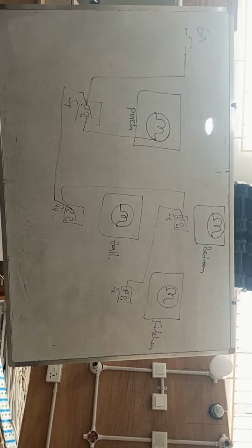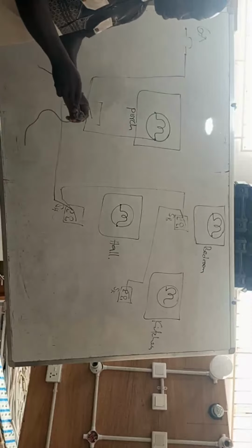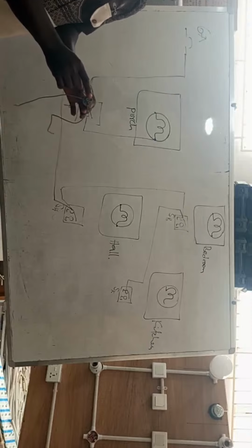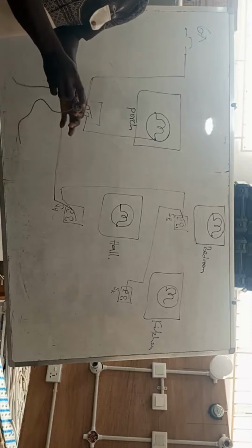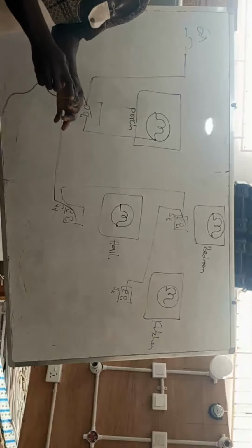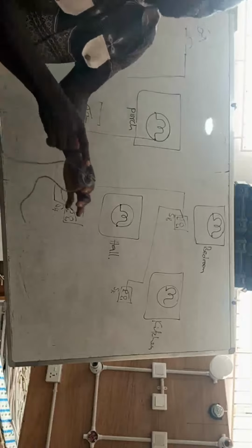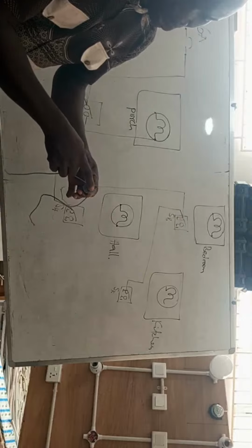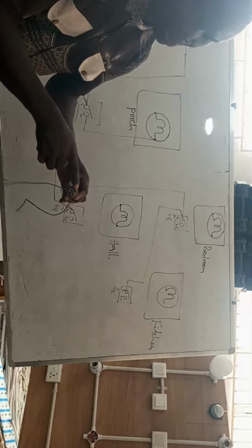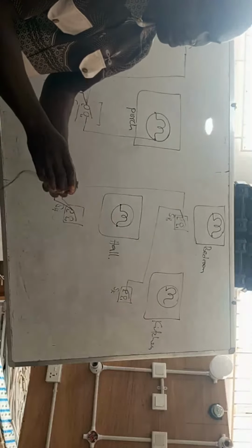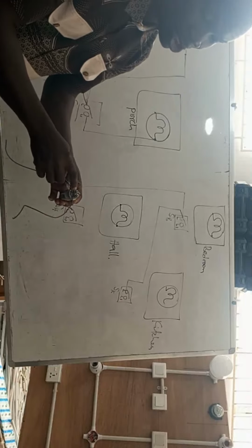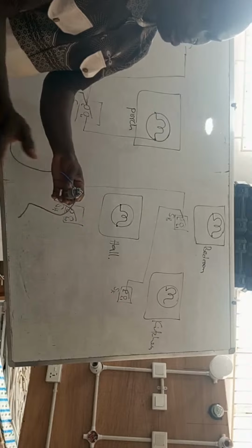Okay, so typically, when you take a lamp holder, these are the terminals you are going to see. You are going to see terminals like this. So here there are 1, 2, and then 3. So these 2 are what you connect for the supply.